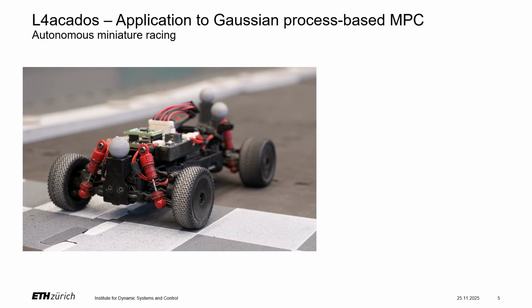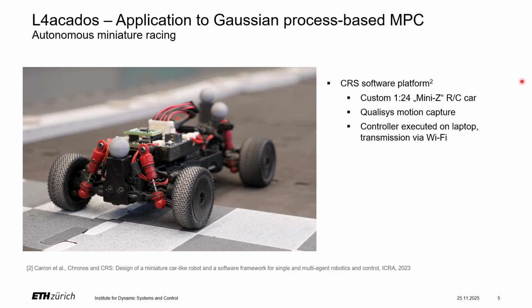The algorithm is implemented on hardware using the CRS platform for autonomous miniature racing. The setup is based on a Qualisys motion capture system for state estimation, while the MPC controller is executed on a laptop, transmitting the control commands to the car via Wi-Fi.